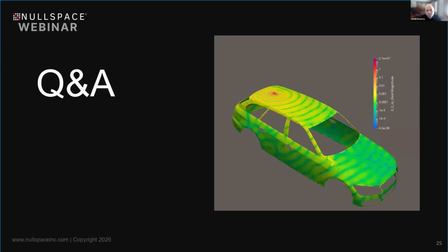In this example today, we had the radome that was covering the shark fin. Even in the standalone case, we had removed that just for the picture, so you can actually see the PFA, but the radome was there in all the simulations that we showed. Yes, a glass fiber radome, and then also the glass roof, of course, that's a dielectric layer. And so yes, there is no problem to simulate any type of dielectric materials in Nullspace.